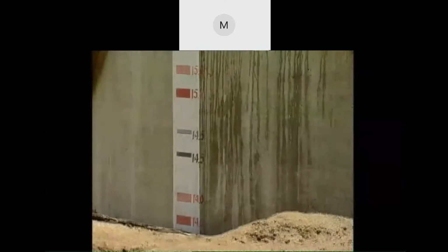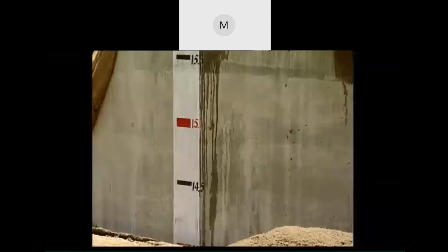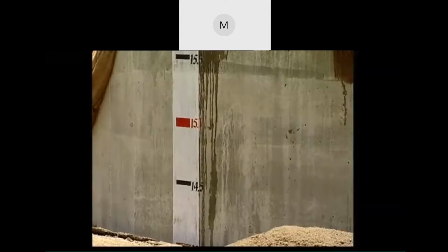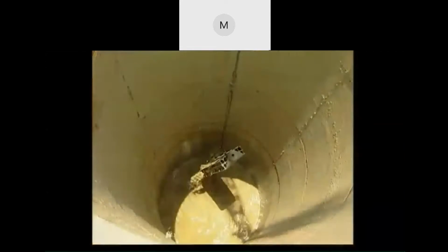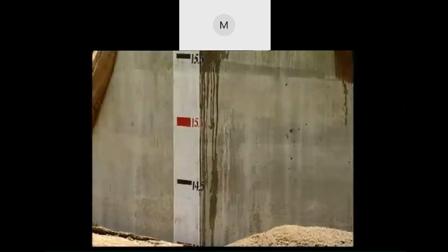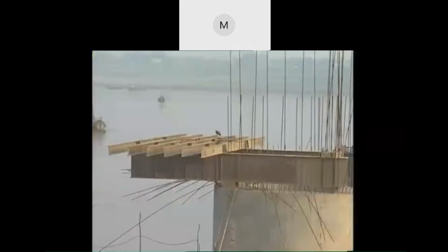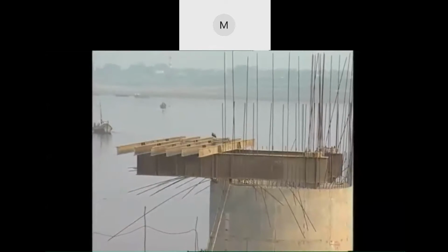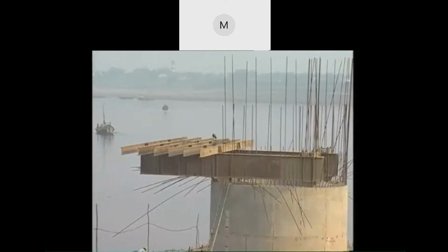Readings are taken during sinking on the gauge marks to measure any shifts or tilts, which, if noticed, are corrected by eccentric dredging or by placing eccentric Kentledge loads and carefully monitoring the movement of the wells.